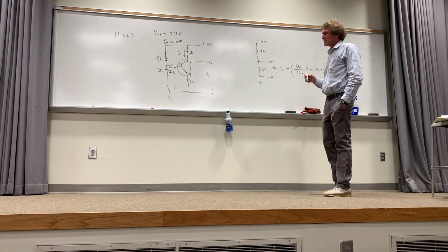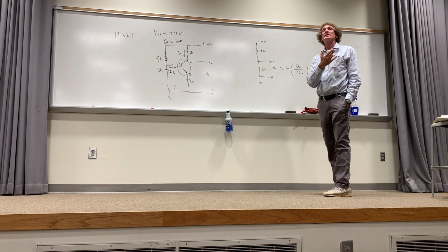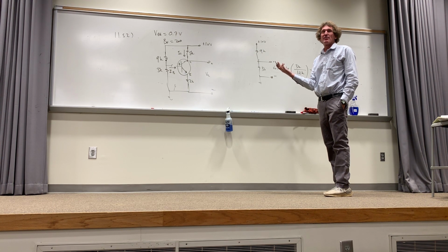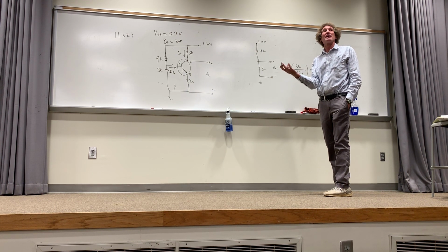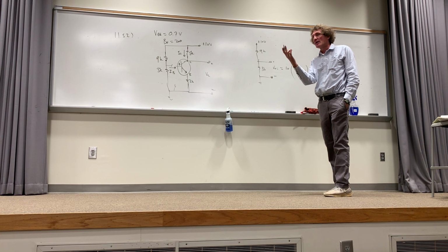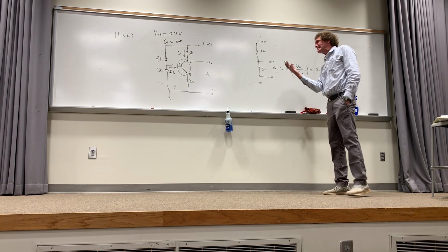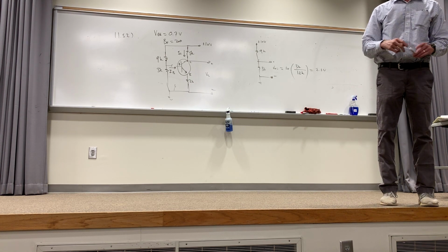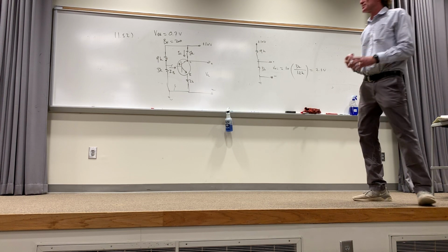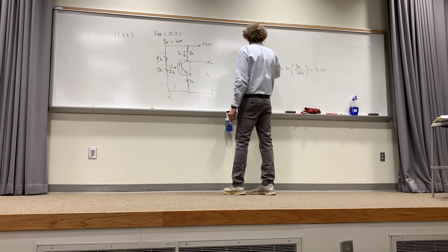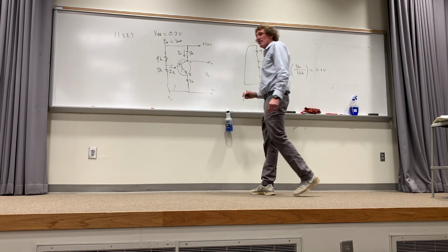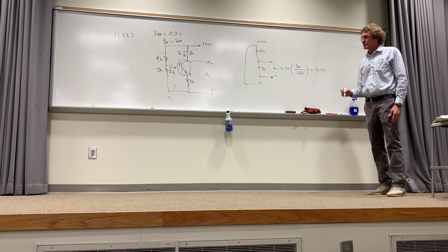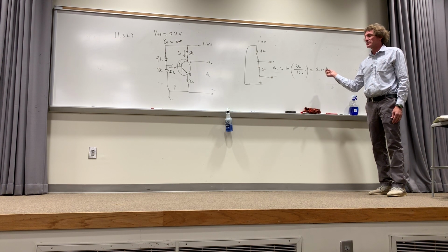What's the next thing I do when I'm doing a Thevenin equivalent, guys? What is it? Say it. Say it again. Turn off the sources? Yeah, sort of, kind of, but what's that word that I'm looking for? The Thevenin resistance, right? I'm looking for the resistance. So I turn off the sources, which means that goes to ground. You with me on that? If you make 10 volts 0 volts, it's effectively a ground, isn't it, class? So what's the resistance between those two terminals?